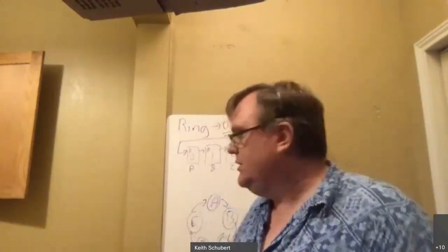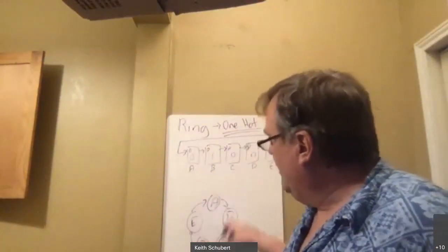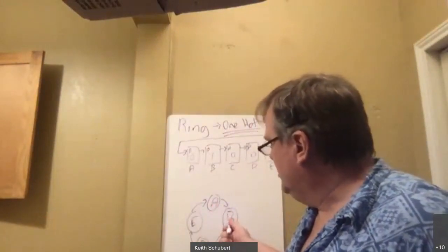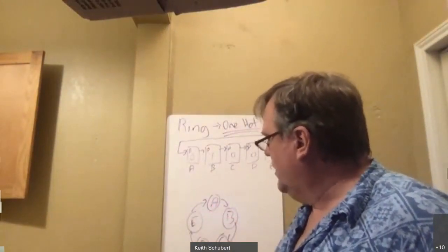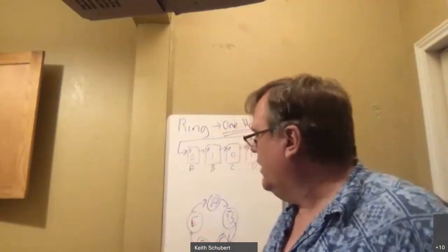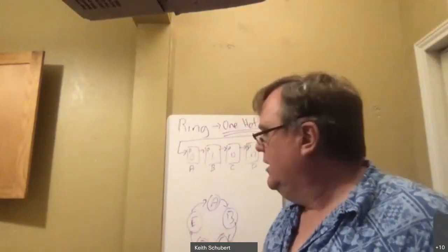So there's 5 stages, called a 5-stage pipeline. We'll have a ring counter that works like this: as the instruction goes through, get the instruction, decode the instruction, do the instruction, access memory, and store the results in your register file. It'll walk through that sequence over and over again.